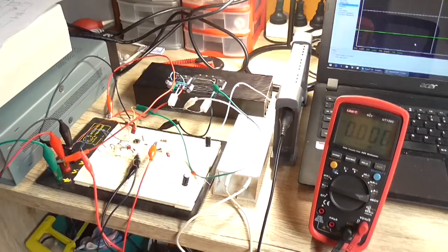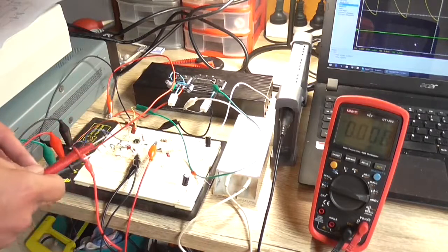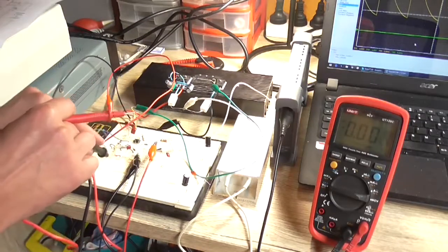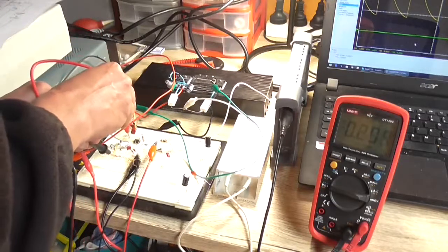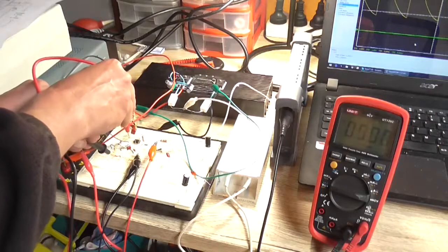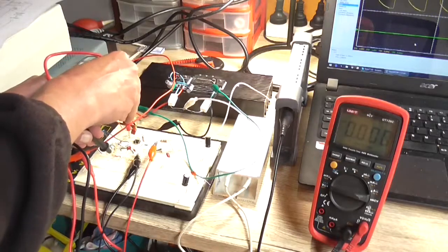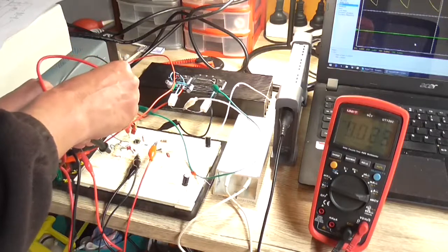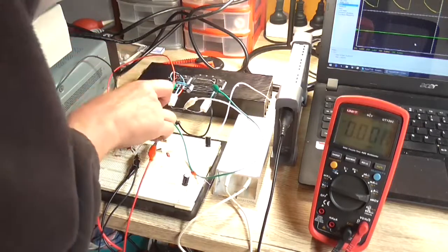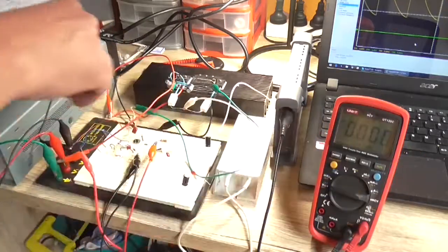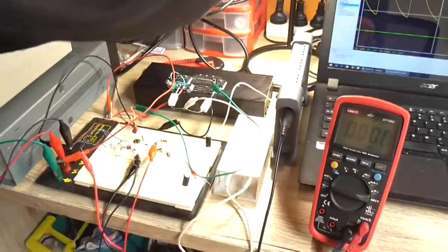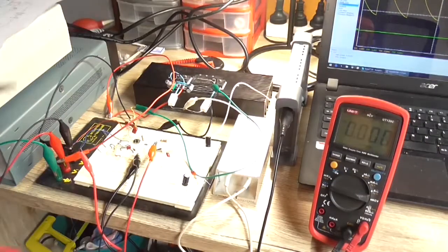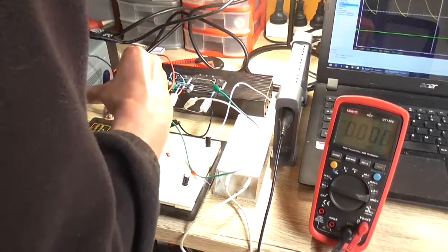Right, so thou shall measure voltages. I'm just going to measure between ground and positive, so that's ground there, and the VCC pin. Well, I can't seem to get a voltage because the wire has come out of the board. That could be exactly why it's not working. I had a pair of pliers here a while ago and they seem to have disappeared, but that wire is not actually sitting where it should be.